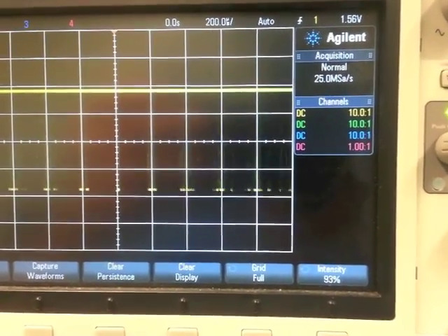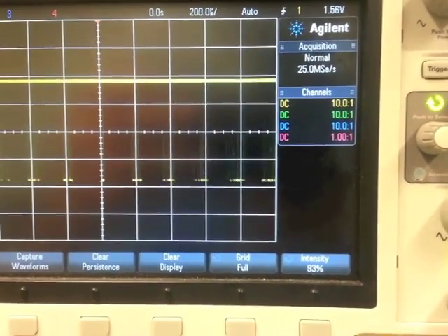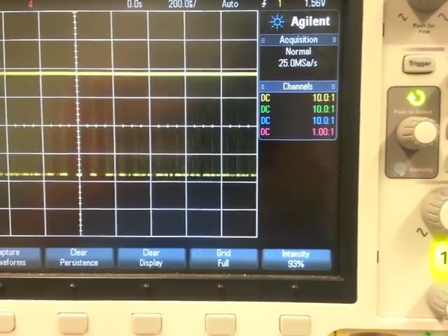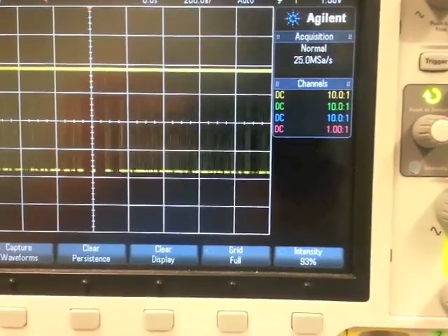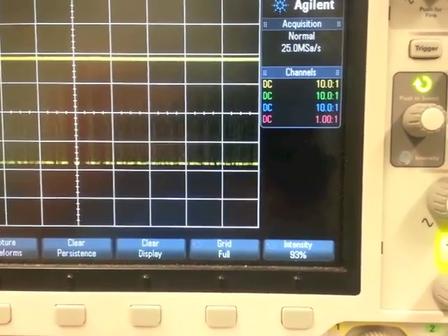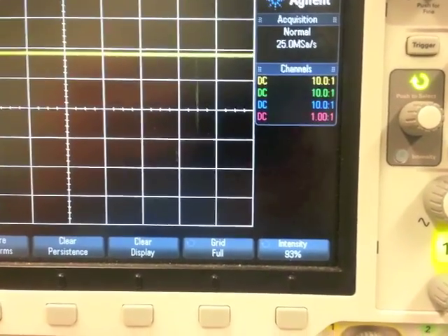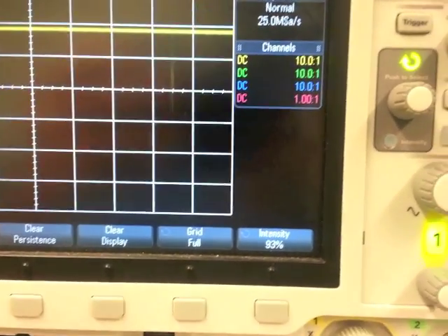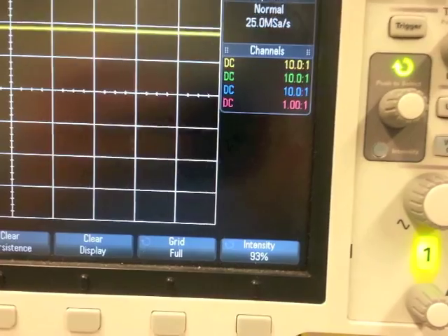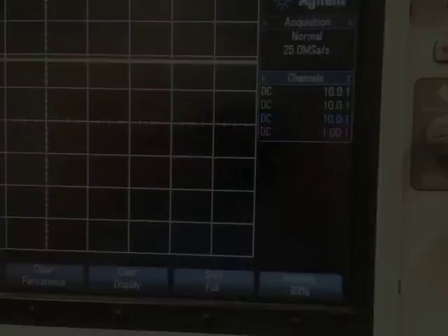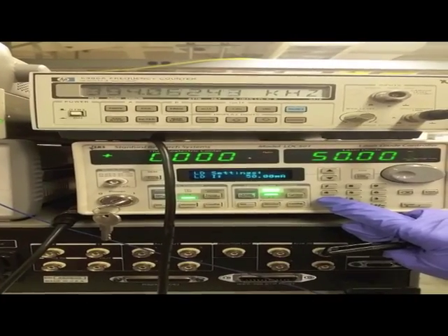Shown here is the oscilloscope output of the pulse train from an individual pixel. As we increase the laser current, i.e. the intensity on the photodiodes, you see the frequency of the pulse train increase. Decreasing the laser current produces the opposite result, and you see an increase in the spacing of the individual pulses, i.e. a lower frequency.